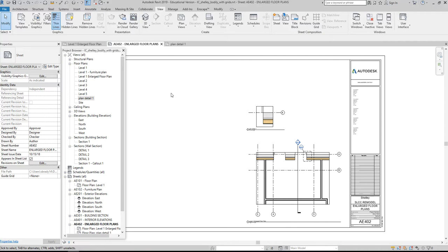Why are you doing this so early, before you place toilets and bathtubs? Because now wouldn't you have to do it in both? No. Wait, they're in there. Toilets are an actual component. It's an architectural element. So if I place it here, it'll show up in any view that it's created. Yeah. It's just detail items that don't show up. So text, dimensions, and detail components. Yeah, everything else will show up.